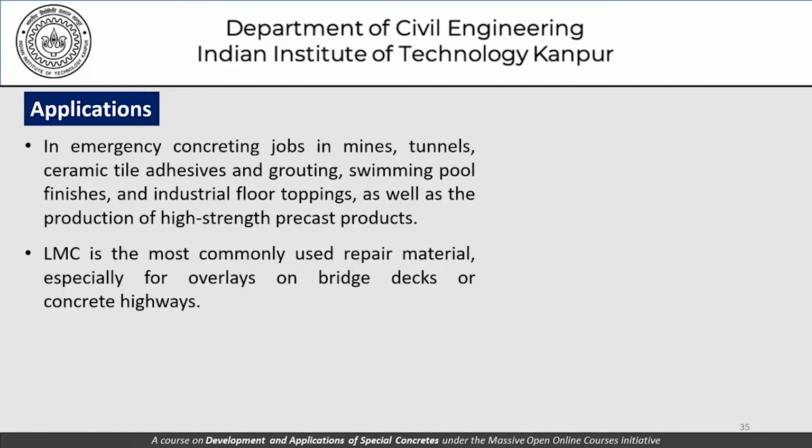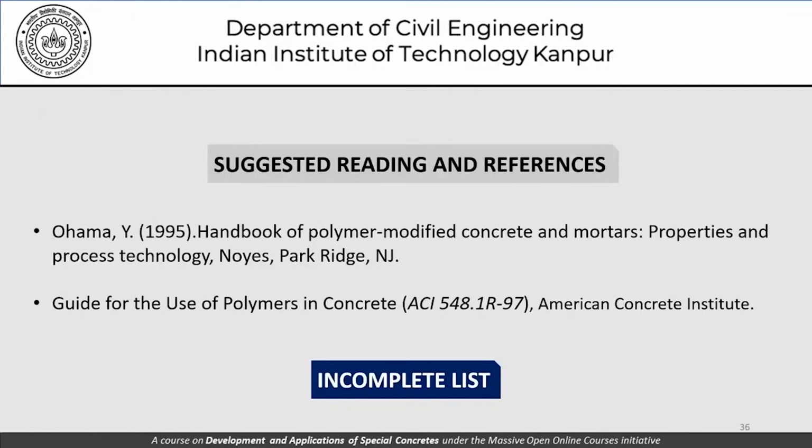So with this, we come to an end of our brief discussion on the three applications or the three classes of applications of polymers in concrete: the development of polymer concrete, the development of polymer impregnated concrete, and the development of latex modified concrete, which have very subtle nuances in terms of applications of polymers as part of the hydration products, replacement of the hydration products in a certain area, or supplementing the hydration products in a certain area is concerned.